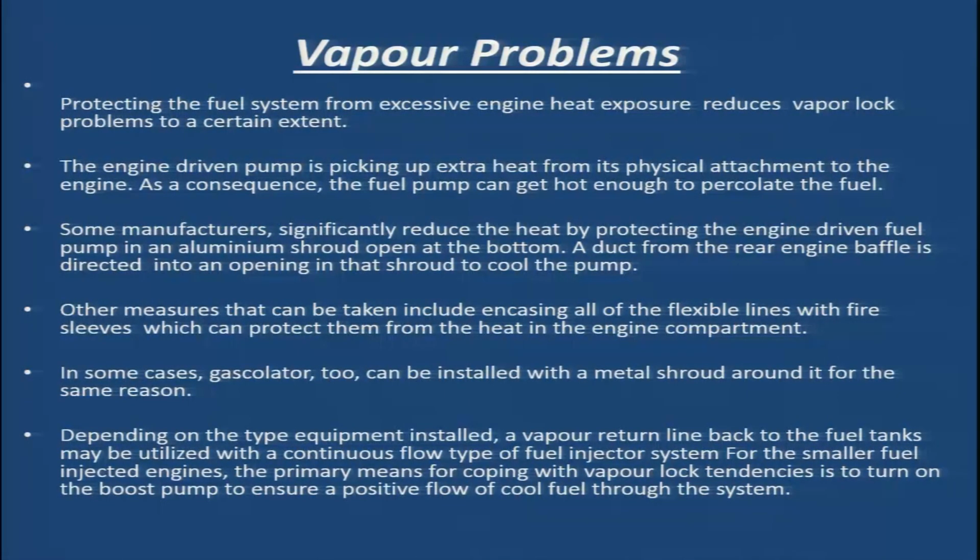But still, apart from flexible fuel lines, we have stainless steel lines running over the cylinders on top of the engine. These metallic lines absorb heat and the fuel gets vaporized in these lines. So, this is a major problem.